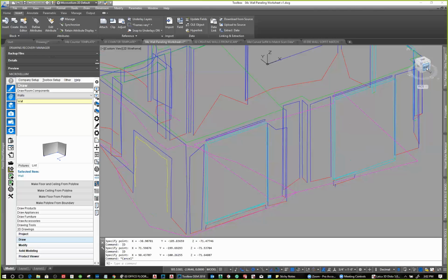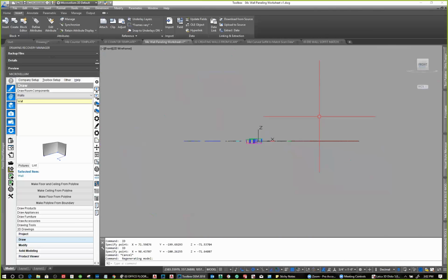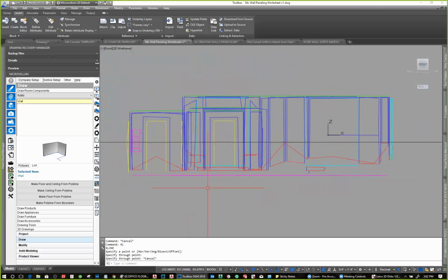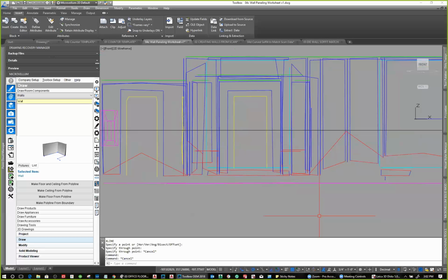You can also use a list command, but you can also go in and see from a side view. I can put in a line, and this line can be similar to a benchmark, if you have ever used one of those when you're measuring with standard tools. So once I've created this benchmark, I can take this view and either flatten it and then start adding measurements to see how off the height of the floor and the ceiling is.